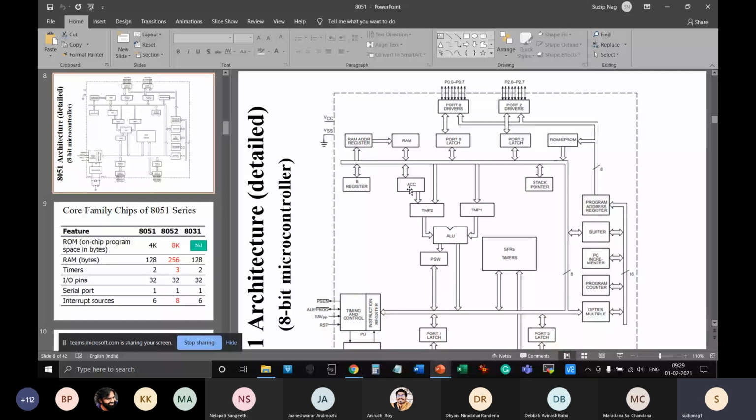Assuming something had happened before ANL which kept some value in the accumulator, that value now gets copied to TMP2. It is quite intuitive here. TMP1 has the value from RAM, and the accumulator's value gets copied to TMP2.